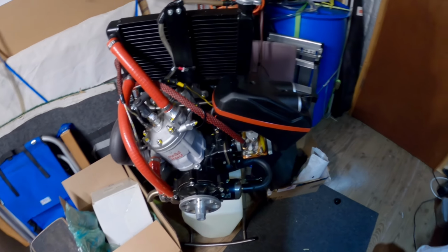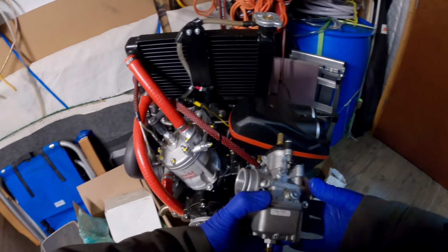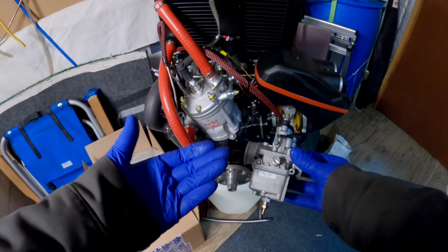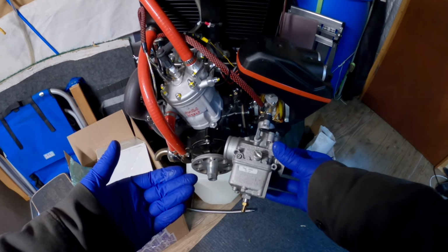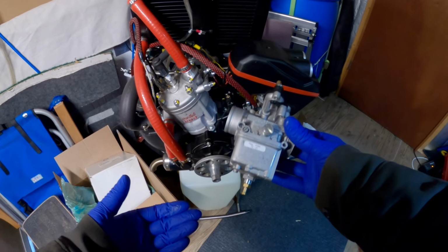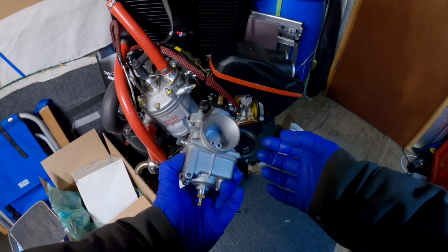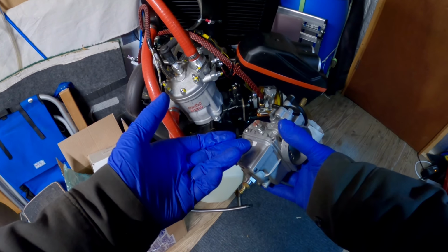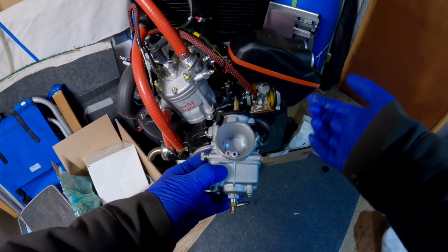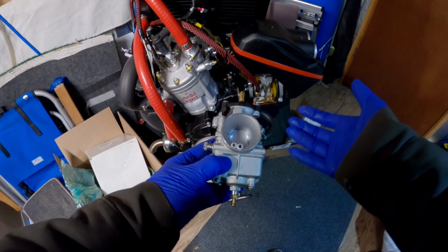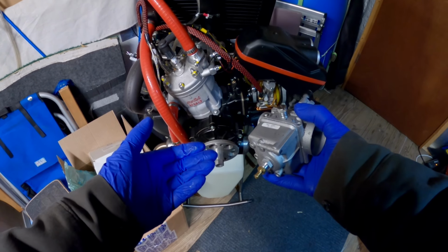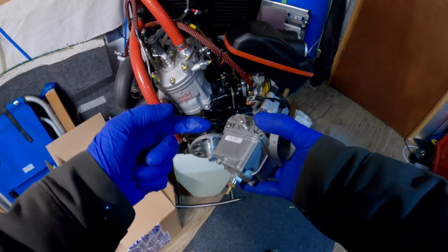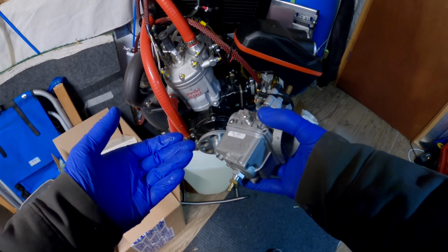Why would I take a perfectly good carburetor like this WB02, which is capable, proven? I'm not going to talk any smack about this. It works. It does work. The problem is I'm in the States, and there's no good source for needles and pilots or anything else, throttle slides, different cutaways, things like that. You can find the main jets, and that's what everyone is leaning on too heavily, the main jets, where I'll show you the needle does most of the work.